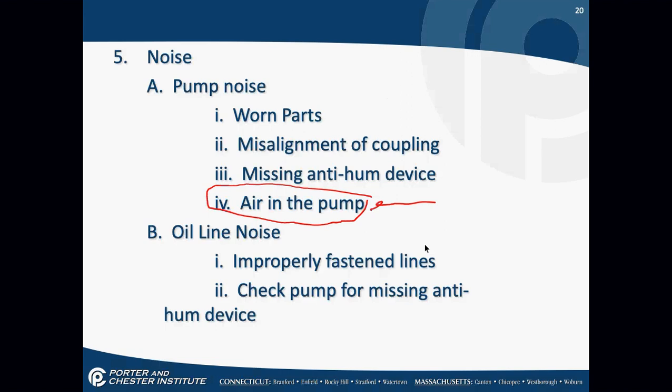Making sure they're properly in the jacket that's required for new oil lines, either the plastic or the rubber jacket. Again, there's an anti-hum device in some of the pumps. Most of them it's built in these days. Don't have to add it. But oil line noise is a real thing, especially when the pump shuts off. The oil line, when the pump shuts off, will jump around a little bit if it's not fastened.